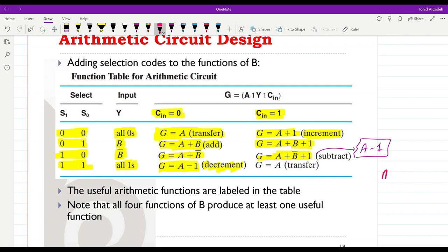If we are going to have A plus 1, 1, 1, 1, then you look at plus 0, which is Cin. If you perform the addition and then you compare it with the decrementing, I'm sure that you will get it. I just let you do it on your own. And finally, when we have Cin equal to 1 and all 1s, indeed we have A plus 1, 1, 1, 1 plus 1, this will be equal to A itself.